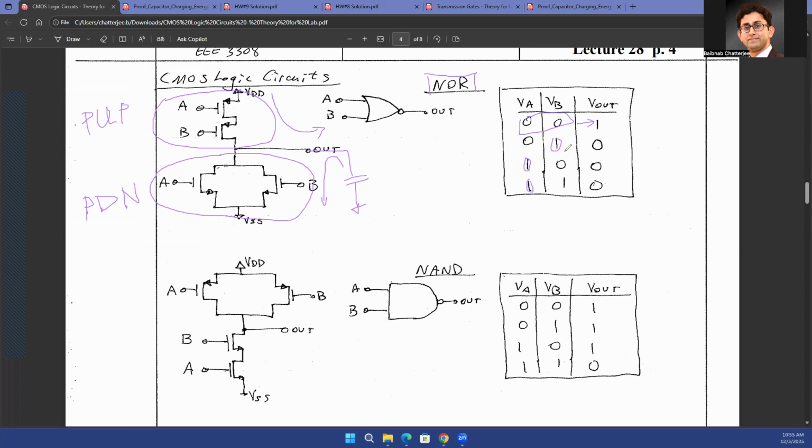So how do you implement this? What it says is that if any of the inputs is equal to a digital 1, discharge the output to 0. That directly gives you an intuition that, okay, if I can turn on my switches and make, please keep in mind that in this case, for any digital circuits, the transistors will be used as switches.